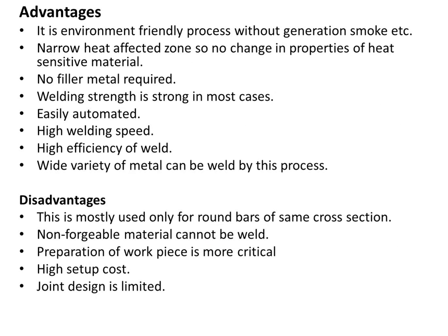What are the advantages? It is an environmentally friendly process without generation of smoke, etc. Narrow heat affected zone, so no change in properties of heat sensitive material. No filler metal is required. Welding strength is strong in most cases. Easily automated, high welding speed, high efficiency of weld, and a wide variety of metals can be welded by this process.